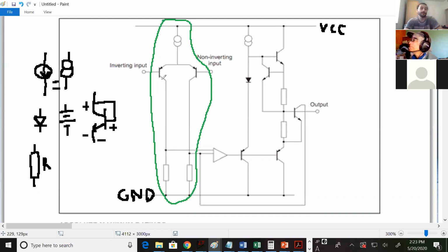What's its job? To have a larger RN. Higher. Yeah, so PNPs actually give you a little bit higher RN usually. And so might as well flip it and get that little extra bonus. But the reason I was not giving you an answer on whether gain is better is that they conduct less current, but they have higher resistance. So if you're using an active load, a PNP probably looks like a bigger resistor than if you used an NPN.